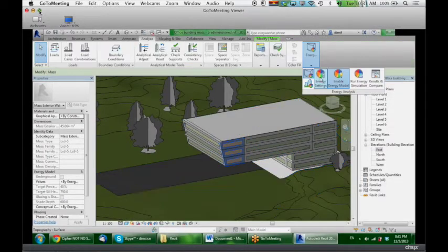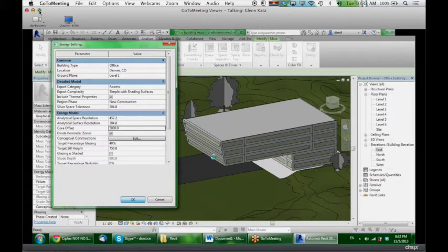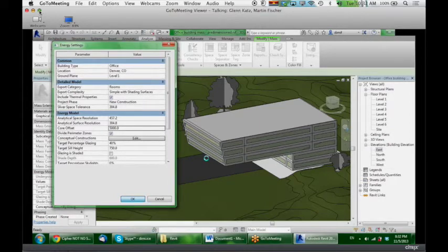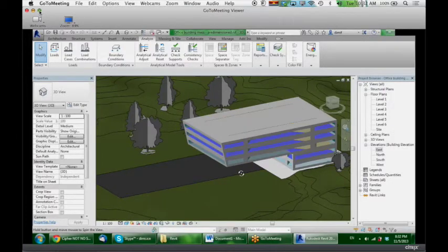The zoning is this thing where, when we get into more detail, you find that a lot of buildings have a separate thermal zone near the windows versus the core of the building. For right now, what DB is suggesting is actually a good thing, which is to just leave that off. Think of it as a big open plan office where there really is no interior wall subdividing it up. We'll get to that a little later when we start controlling the detail. But when we think about buildings, the perimeter is a little different. It's more controlled by the exterior forces than the center of the building.